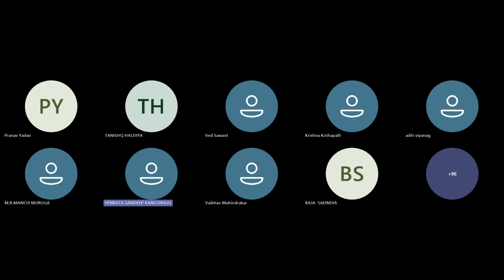There you will get how to create a custom code for each particular model. Could you please explain once again about creating the SKC file step by step? Okay. At the very first, you need to run your analysis under IPG kinematics. Once you run it, you will have a number of files in the project folder where your kinematics directory is present.